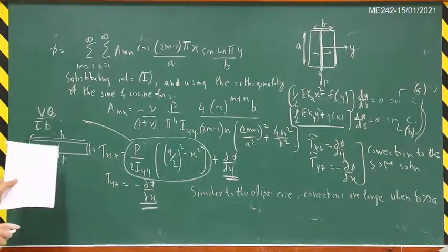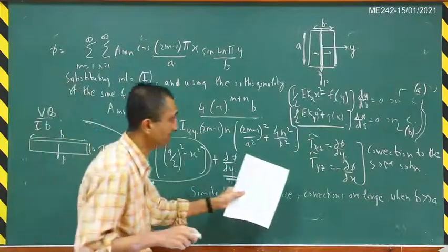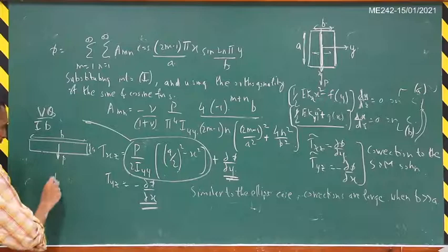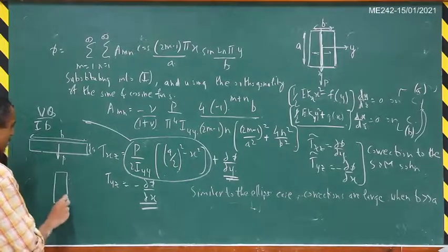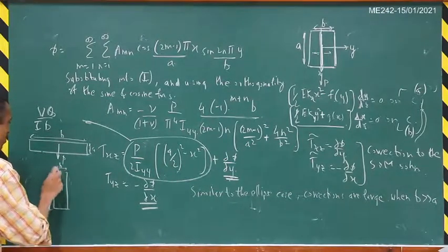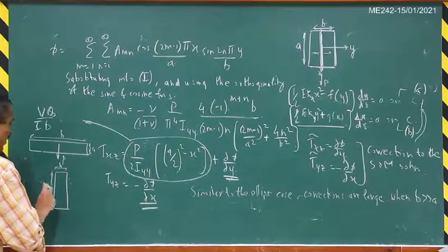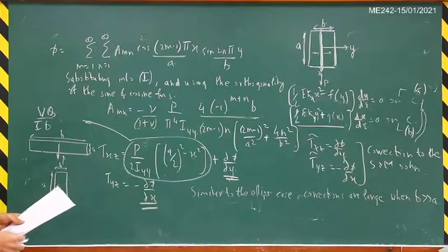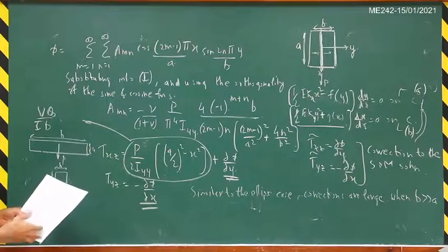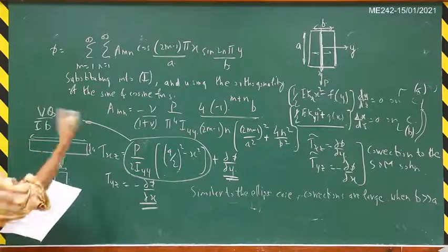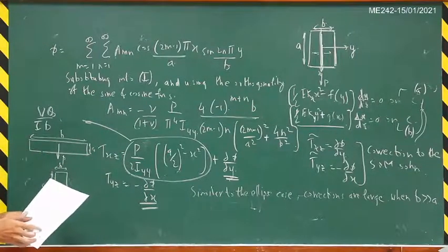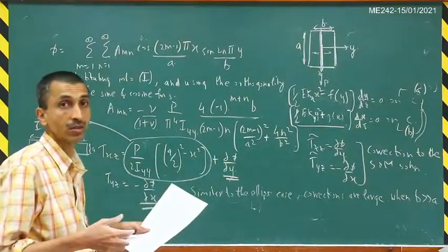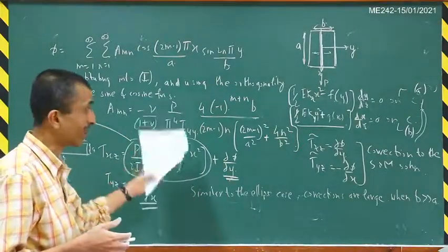And then, so you have to go to the exact solution when you have a case like this. But if you have the other extreme, which is like this now, so that is, this P is now small compared to A, then in that particular case the strength of material solution is a very good approximation. So because we now have the exact solution, we can judge how good these strength of materials approximations are.